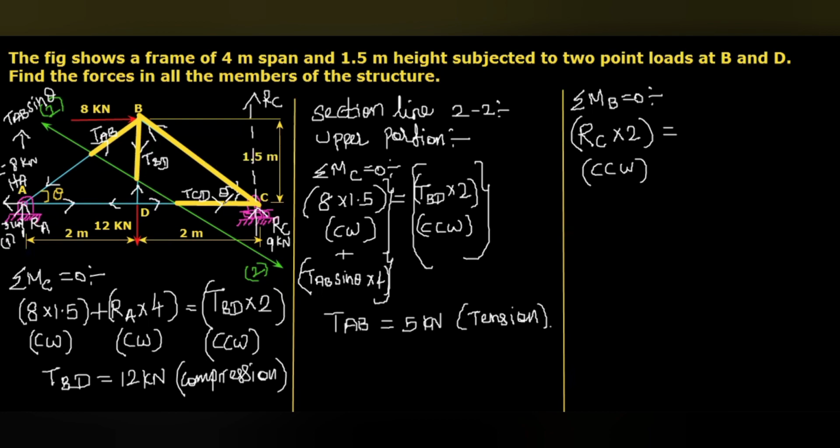If it acts inwards to the C, that is towards the right side, then the moment made by TCD is also counterclockwise with respect to B. So it will not act towards right side because we need a clockwise moment. So it will act outwards from the point C. So from point D, it will be this side. So from point B towards left side.